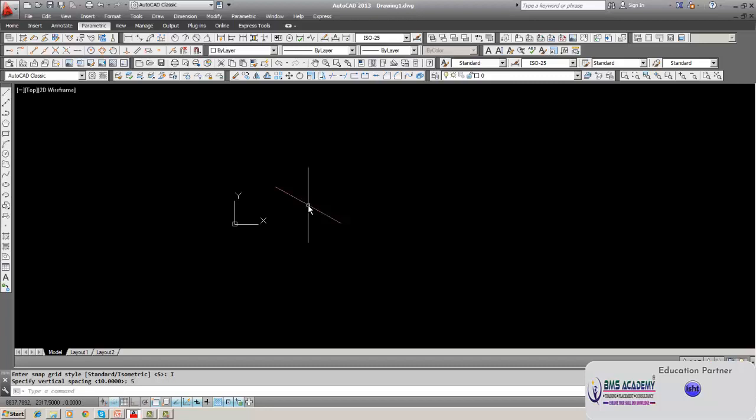Okay, now you see on the screen the cursor is inclined at an oblique angle as if it is on one face, on the left face. And I can change the cursor shape or orientation to a different orientation by pressing F5. See, it has become top. This is called top. The cursor looks like this. Here the angles are 120, 120 and 60, 60. And if I press once again, you just see it comes to the other face. Orientation will be opposite to the first one.